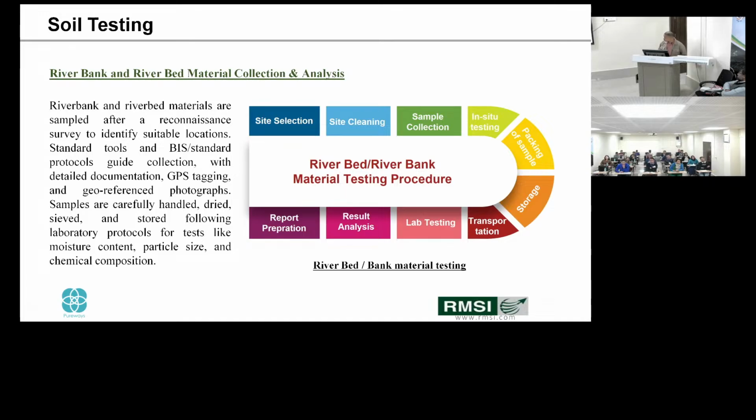This slide will show how we will collect the soil sample. Mostly the soil sample is collected at constant intervals, like per 10 kilometer, per 30 kilometer, as per the requirements of the basin. Where there are plain areas where there is no undulating terrain, we prefer mostly a distance of around 50 kilometers on the main stretch of the river. But if there is an undulating terrain and the topography changes for every, let's say, around 10-20 kilometers, then we have to minimize the gap of our soil sampling areas.